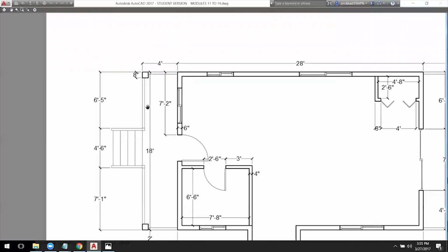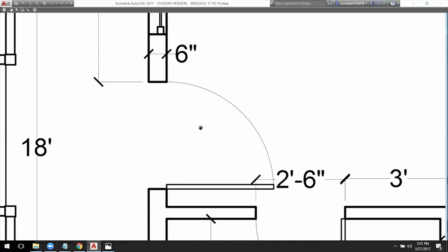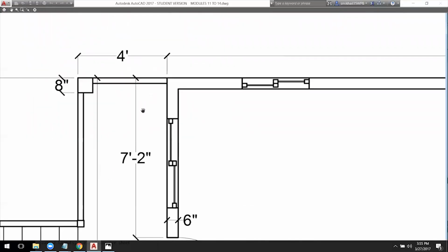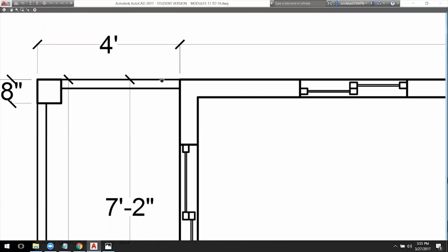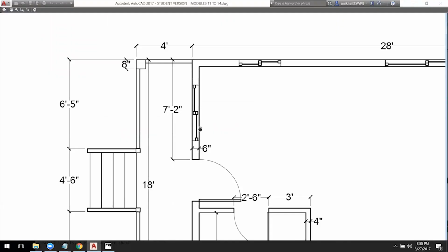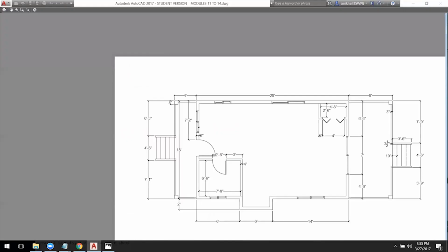Seems like some of the line weights is not so clear. So the door swings come out very nice and light. The difference between the panel and the wall is very nice. The glazing, however, not so much, and the railing, not so much. The railing must be much lighter because we're not cutting through it, it's low, and the glazing should be much lighter than that. And also the frames are very thick. So let's go back and see where we went wrong.